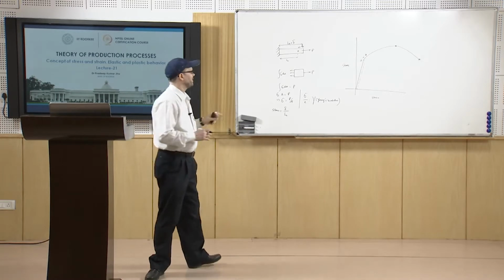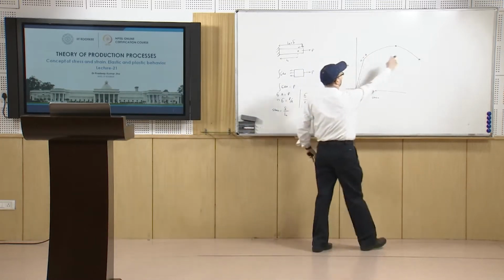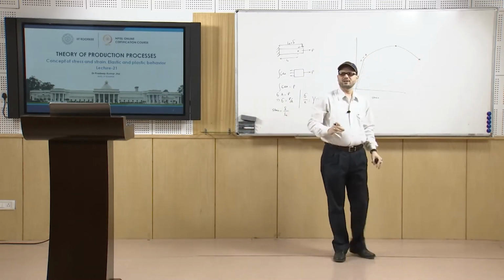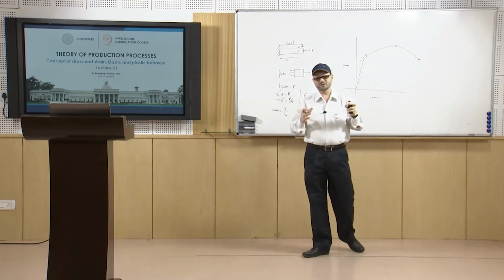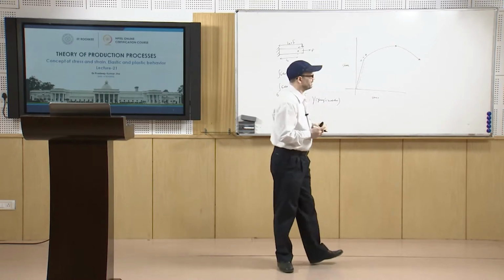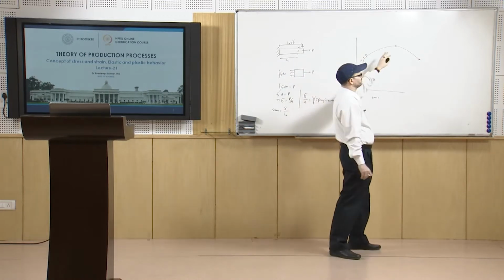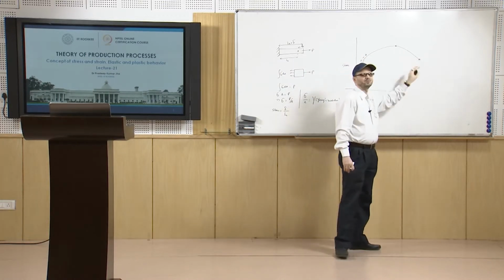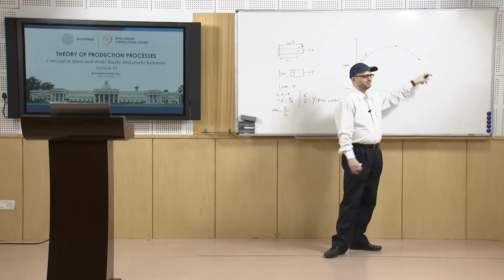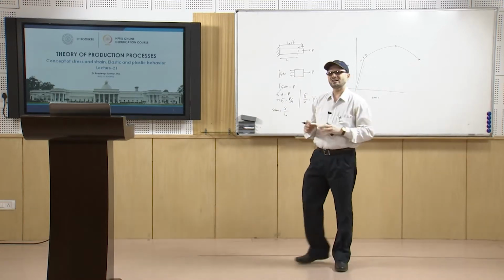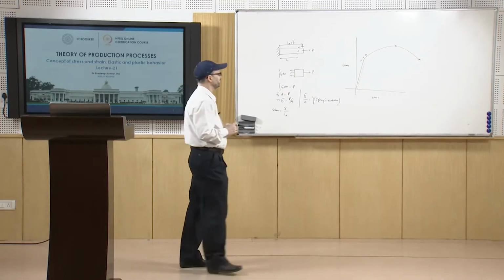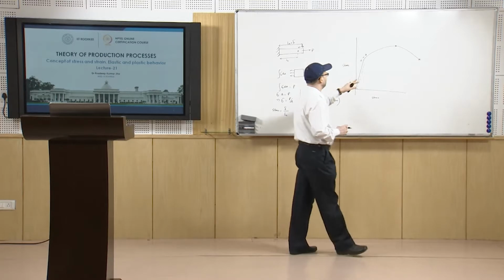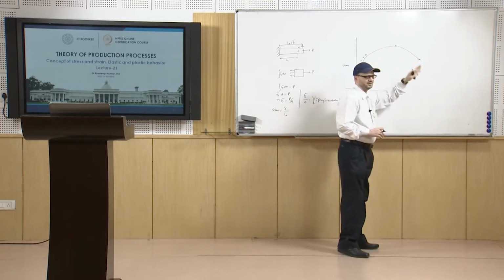So, that is why this curve comes down and then ultimately it fractures here, because after this point the area is decreasing at a very high rate, and that is why the load comes down, and so the stress value goes down, and here the specimen fractures. So, that is how it occurs. This is the tensile behavior of ductile materials.